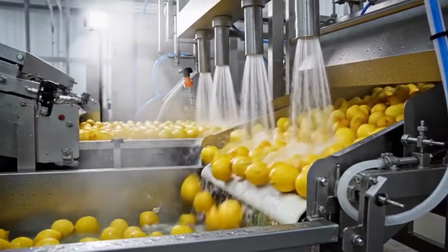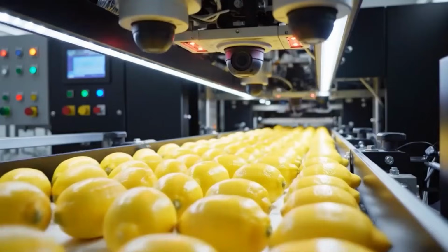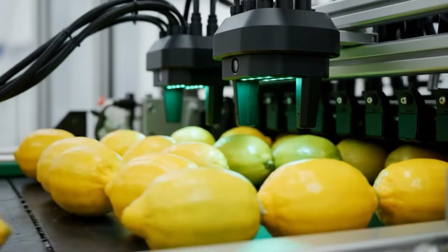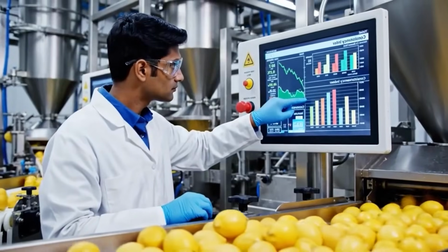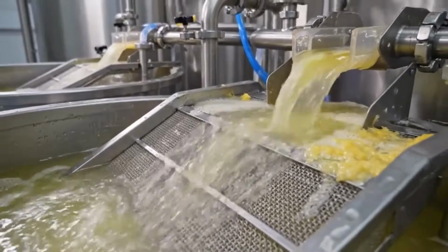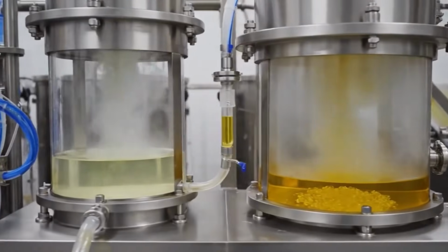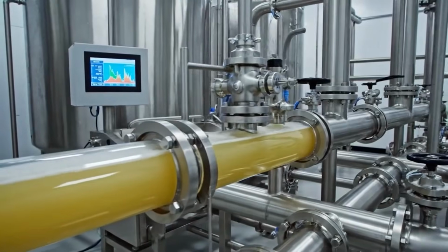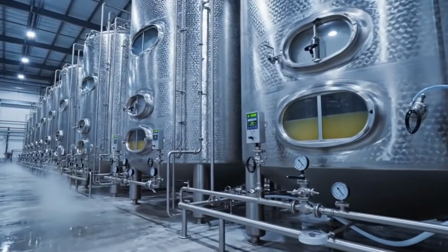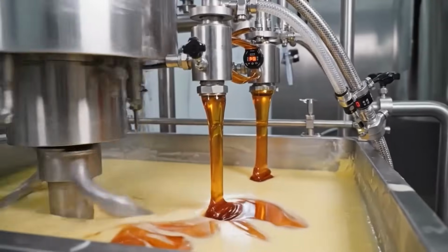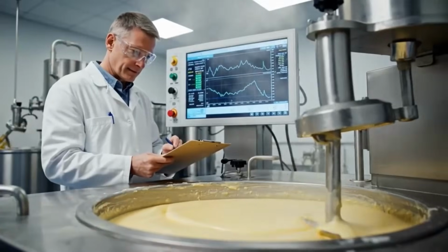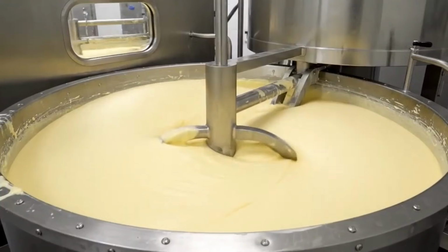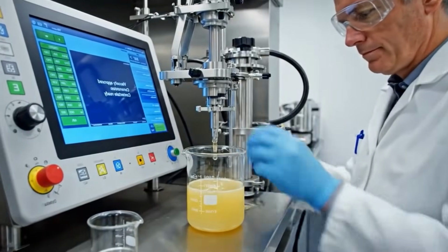At this stage, air is injected into the freezing chamber to achieve controlled overrun. For sorbet, overrun levels are typically between 10 and 30%, maintained using mass flow controlled air injection, synchronized with product throughput. Air pressure, temperature, and flow rate are logged continuously. The exit temperature of the product from the freezer is typically -5 degrees Celsius to -7 degrees Celsius, with a soft serve consistency suitable for depositing.